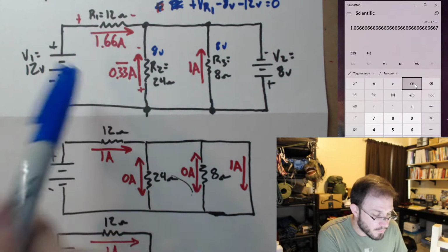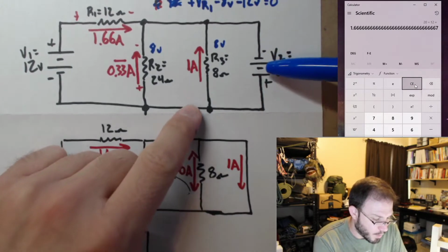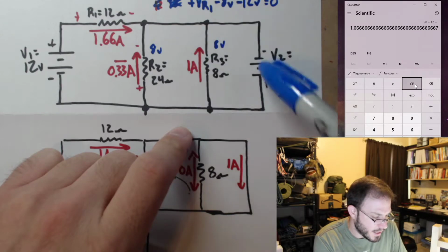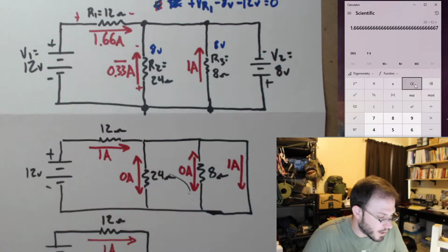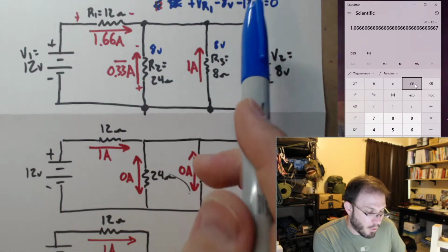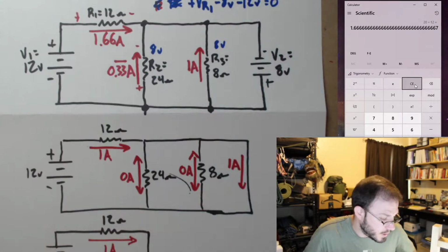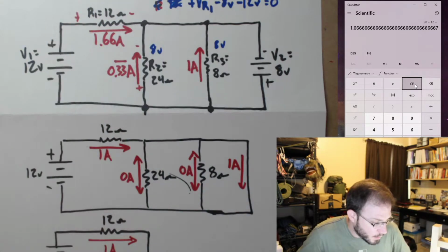It wasn't as straightforward to see as, say, this 8 ohms, where I only have one voltage and one resistor in this loop. In this case, I had a few different things going on. So that's one of those cases where I'll write it out to make sure that I don't screw up Kirchhoff's voltage law with its application. But it confirmed exactly what we got.